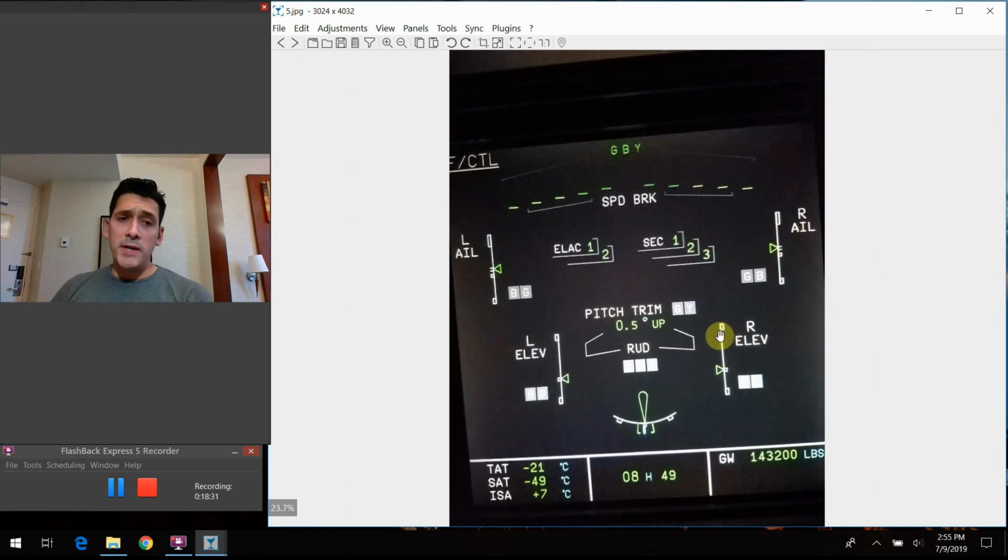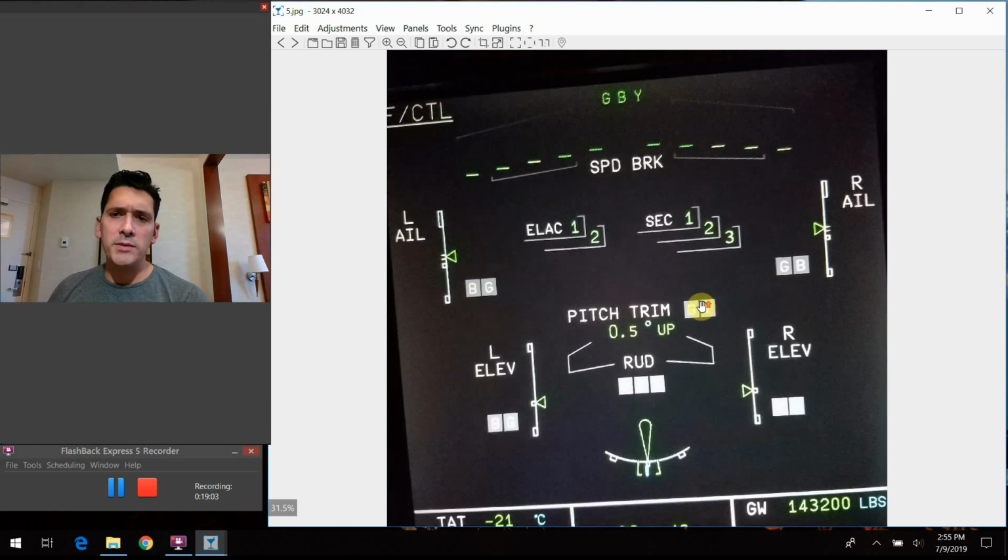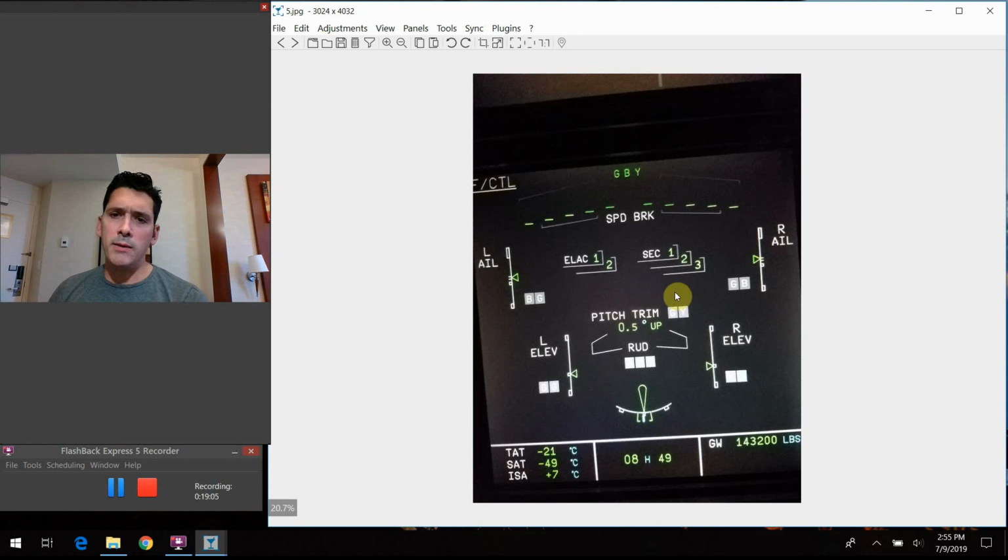And it backs up and drives home that point that the whole reason why this is designed the way it is is because of redundancy. We need to have a way to keep flying the airplane if we were to lose one of these hydraulic systems, totally take it out of the loop because there was a leak or a break or something catastrophic happened. We still need to have a way to manipulate the flight controls, of course. This is very important for us to get the plane safely on the ground. So, like I said, just a little add-on to give you some detail about what that looks like and what we're looking at in our normal flying scenario.